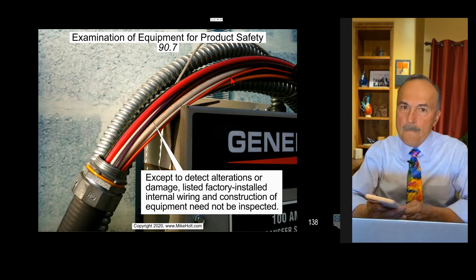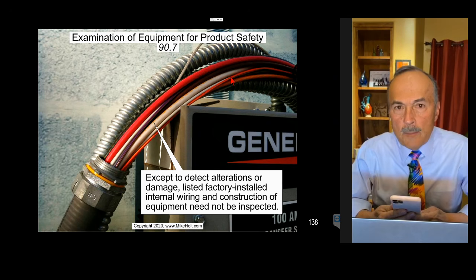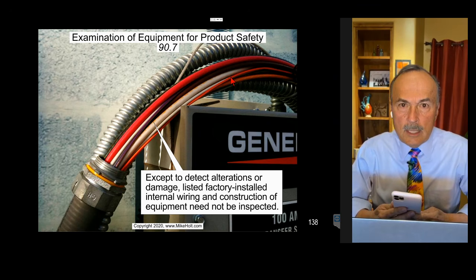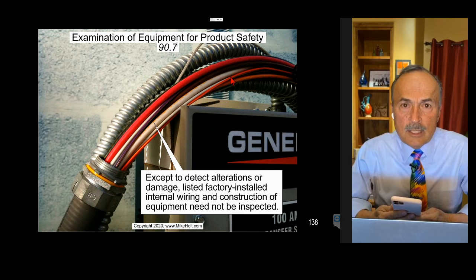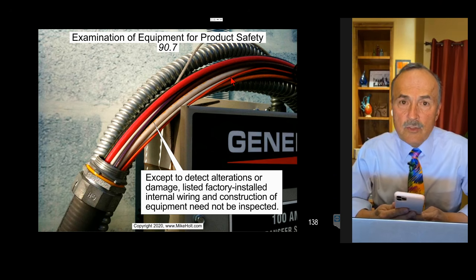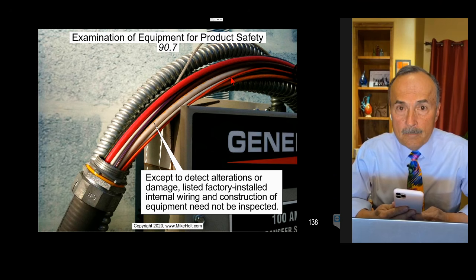That used to be in the existing panel. So I'm only going to be running wires that were off the breakers in the existing panel. I just connect those to the wires that are going to this generator transfer panel. Right? Yes. Okay.